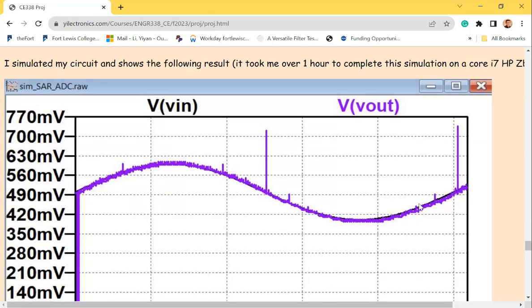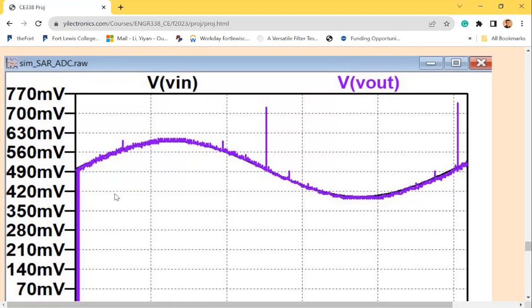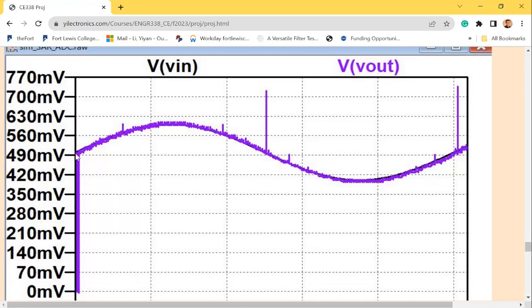Okay, it does give you a sine wave, and in the first cycle, you turn on the ADC, your music signal comes in. That's exactly just the first cycle, just the first period of your music signal. You keep it on, there are thousands of waves at least after that. So you are seeing a huge dip over here. You are concerned the ADC is not working properly. No, it's just that when you turn it on the first time, everything's getting reset. You are expecting the very first digit or the first data, and it's not whatever you expected.